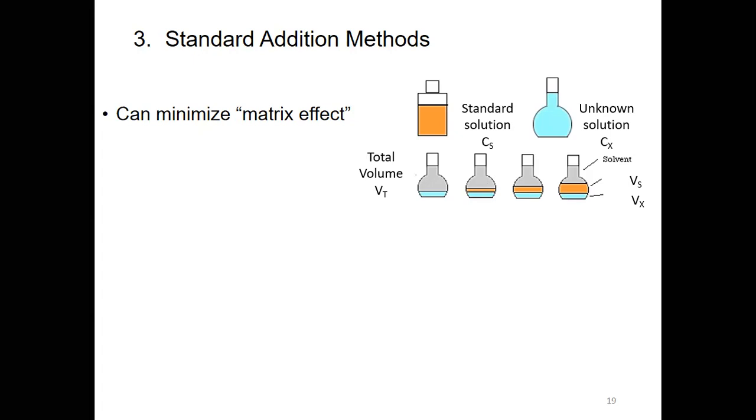To prepare a plot, actually, even with two data sets we can draw a graph, but you should have at least five individual data sets to prepare a calibration plot. The more data points you have, the more accurate the calibration plot.